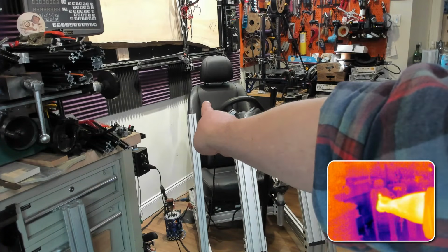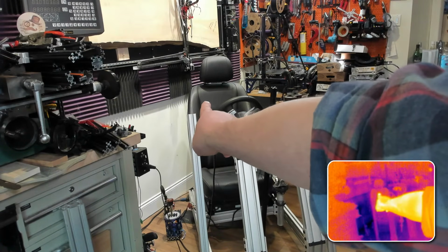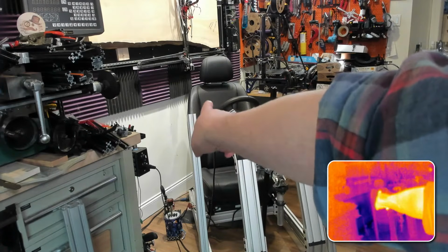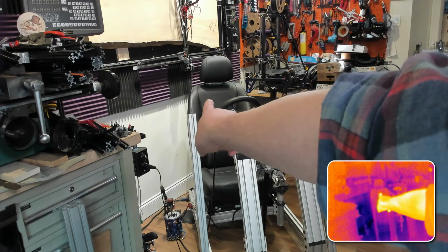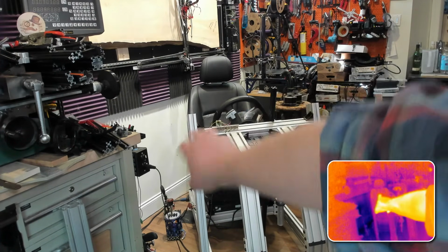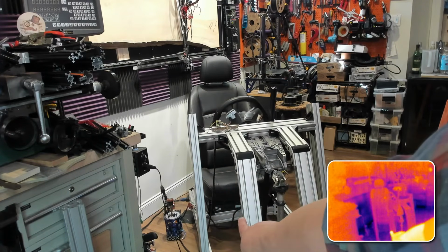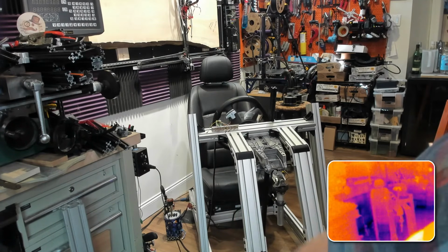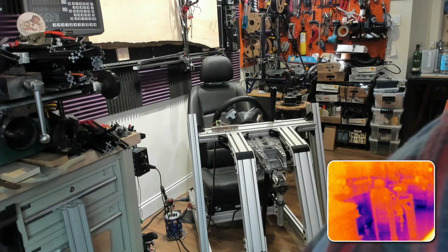these are popular chairs with simulator setups. They're pretty easy to hack into. They've got some cool stuff going on for them. Mostly, though, people don't really hack into them. They attach them to either their classic car or the simulator setup, and then into the CAN bus line at the bottom, they will inject a 1 kilohertz square wave. 100 kilohertz, I don't know how many. They inject a square wave into the CAN bus line, and that keeps the seat alive so that you can adjust it at all times. It's too bad it doesn't work on its own, but generally when you boot it up, it goes, I'm not attached to a car, and then it goes to bed.